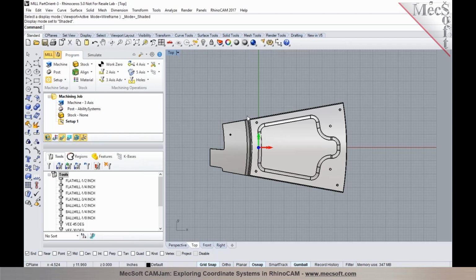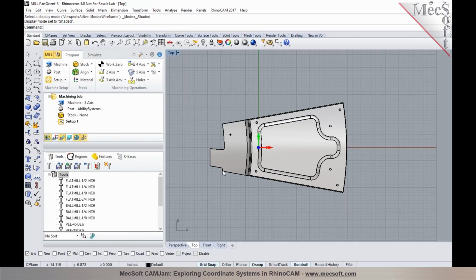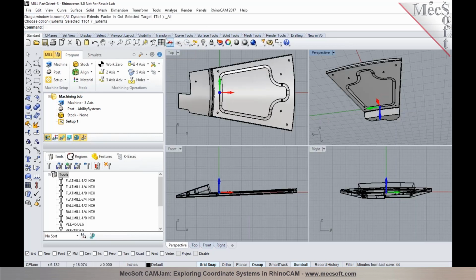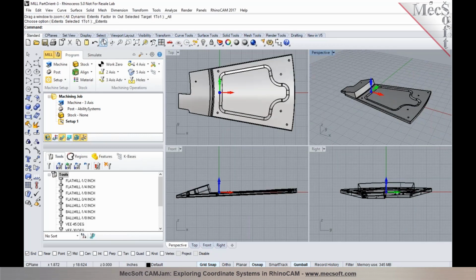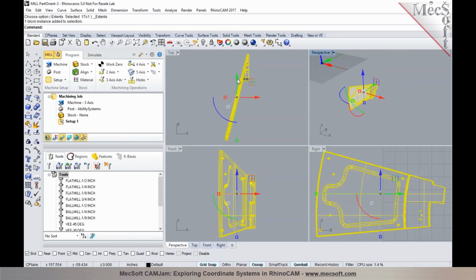So this is one of the ways how you could perform the transformation in CAD using transform, orient, using 3 points. There could be several other techniques or other ways to do it. I just chose one of these ways using 3 points, similar to how we did it in Visual CAD/CAM. So now we can tell that the part is oriented. Now if I go back and perform an undo on this operation in here, I'm going to undo this. So you can see that the part is back the way it was imported.